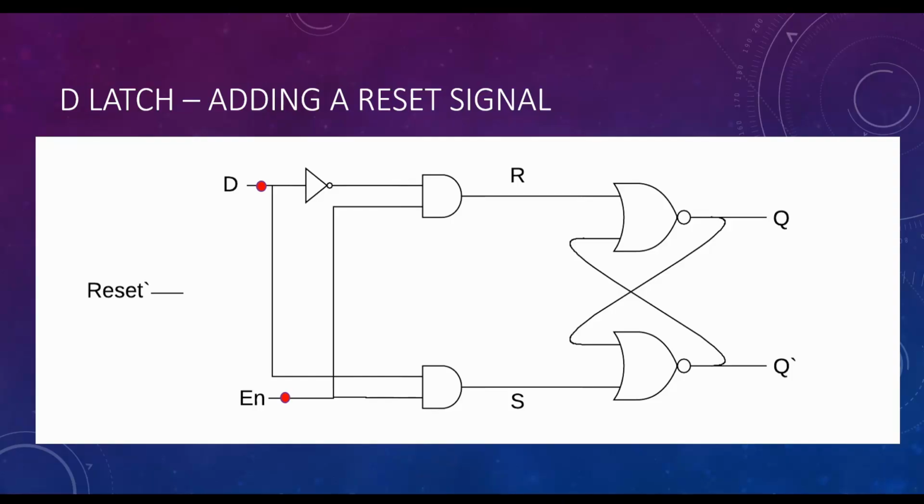Okay, that was quite a journey. I hope you have survived it, but I'm going to be a little bit greedy, and I want one more thing. I want a signal that will help me reset the latch at any time asynchronously. So that's my reset signal. It's active low, and therefore there is a tag on it, meaning it's active when the input is 0.